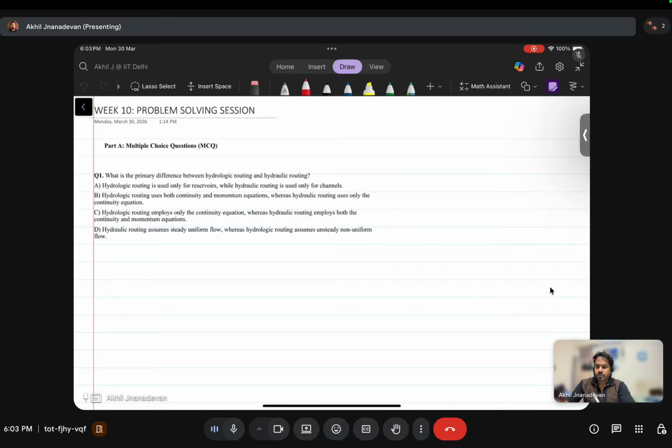There are different tools that are used to derive one particular storm unit hydrograph, and from it another unit hydrograph for another duration of storm. And we saw different hydrographs like S hydrographs, which are generated due to a step input, that is rainfall that goes from 0 to 1 at t equal to 0 and remains 1 indefinitely.